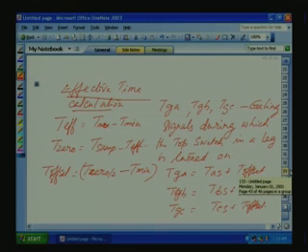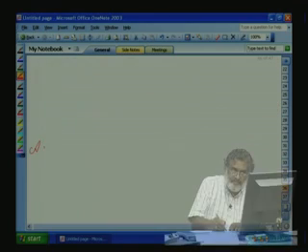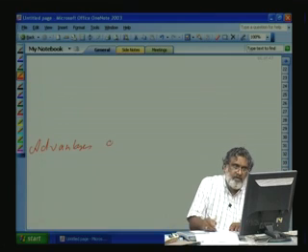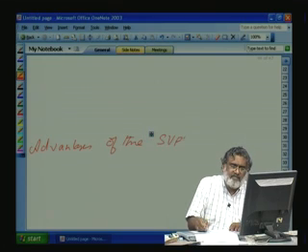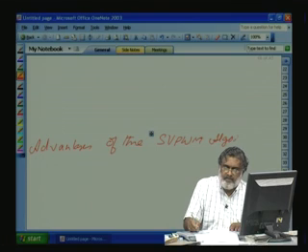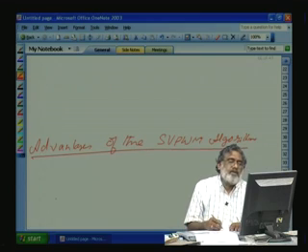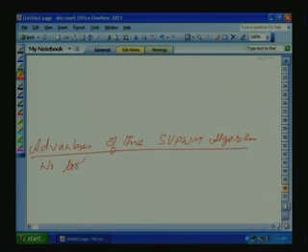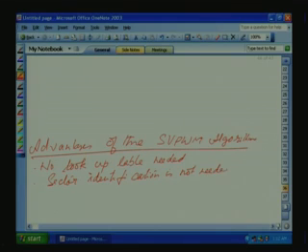So this algorithm is very simple. The advantages of this PWM algorithm: No lookup table is needed. Sector identification is not required. The angle alpha with which the reference space vector makes with the start of the sector, the alpha angle information is not needed.